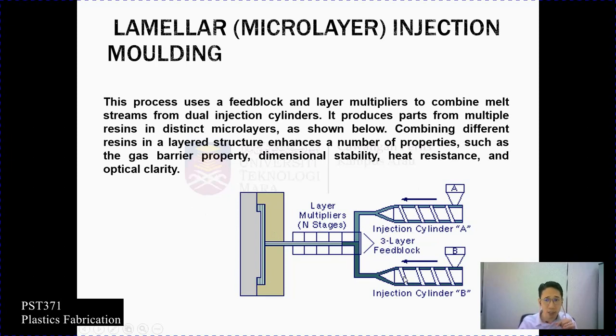Okay, injection units, and each injection unit has a different material. And when each injection unit injects the raw material into a cavity, they introduce different properties because of the material itself, and it will inject with another injection cylinder. The second injection cylinder we call the B injection to introduce another layer. Having this type of injection molding can introduce different properties in one final article.